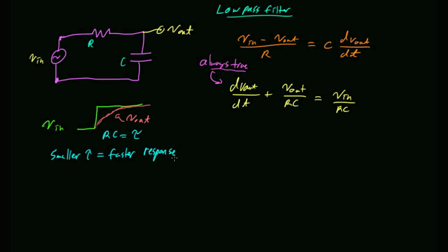I have to use good handwriting because that's going to be on the board for a day and a half now. Good. And then in circuits 2 you learned how to put in a cosine for V in. So if you put in a cosine, what comes out? A cosine. If you put in a cosine at some frequency omega, the laws of the known universe tell you that what you're going to get out is a cosine at the same frequency. No ifs, ands, or buts. And that's the only signal that has that property. The only thing that can change is the amplitude and the phase of your cosine, and there are equations for solving that. So we learned cosine in, cosine out, and that was all cool.